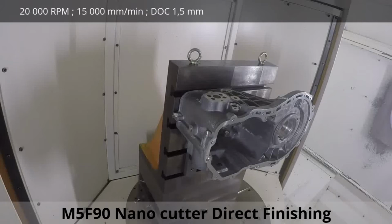Okay, Kevin has got the climb milling video. So we have an example here. We're going to talk about climb milling. In this video, you're going to see the cutter enter the cut and go all the way around the part in a clockwise fashion, offset, like I said earlier, where you're not right dead center. Then it's going to drop down in this center feature and reverse direction, which is still climb milling, but going from inside out. So that being said, Kevin, if you want to go ahead and run it.